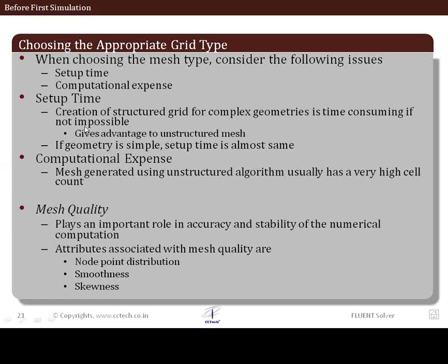What is the setup time involved in creating and generating such mesh? So structured mesh is very helpful. I'll show you a slide about what are the advantages of structured multi-block meshing strategies, how much it can improve the accuracy of the problem. But the other problem is that it is quite time consuming and it requires a lot of skills to be able to generate structured flow aligned mesh. And it is possible on simple geometries, but on complicated geometries it requires a lot of time to set up the problem. So this is one of the factors we'll consider in deciding which kind of mesh we should go for.